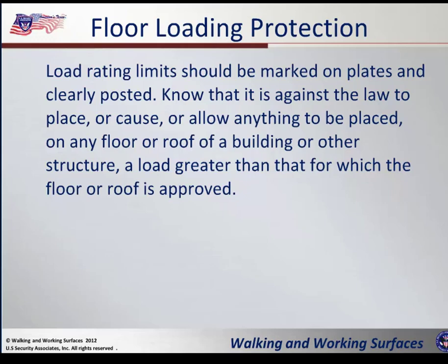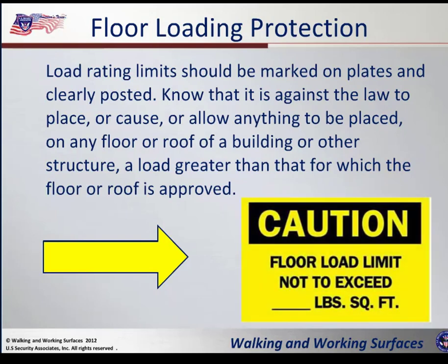You have to know that it is against the law to place, cause, or even allow to be placed on a floor or a roof of a building or any other structure a load greater than that which that floor or roof is actually approved for. So let's take a look at a typical sign that you may see on a wall. This one says, caution, floor load limit not to exceed 300 pounds per square foot.